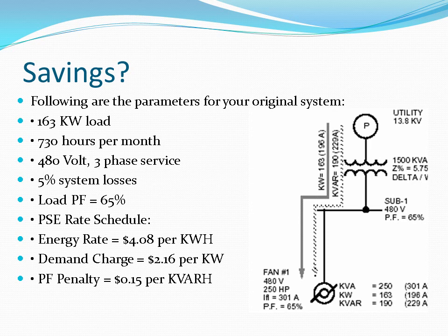163 kilowatt load, 730 hours per month, 480 volt 3-phase service, 5% system losses, load power factor of 65%, PSC rate schedule of the energy rate at $4.08 per kilowatt hour, demand charge of $2.16 per kilowatt, and a power factor penalty of 15 cents per kVAR.